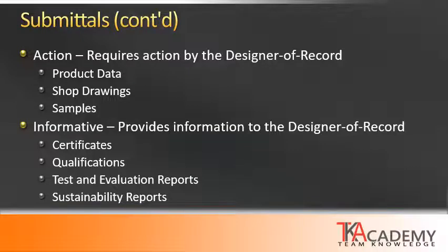Submittals are typically categorized as either action or informative submittals. Action requires an action by the designer of record, not to be confused with designating an action to the general contractor. This is an action that needs to be done by the designer of record. These include product data, shop drawings, and samples. These are reviewed by the architect, usually marked up, with some type of comment provided, something that authorizes the contractor to proceed based upon this review.